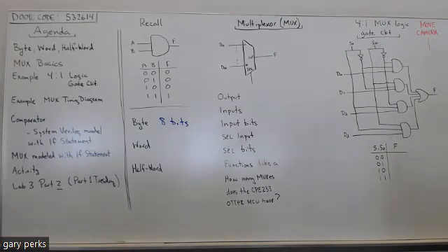So on each table, I put this diagram, and please leave the diagram on the table because I need this for my section later. But this diagram shows the structural model of the microprocessor you build in CPE 233. If you take a look at this diagram, you'll see that quite a few of the lines have a /32. What does a /32 mean on a line? 32 bits. So most of the data that's going around in this microprocessor is 32 bits. And the reason for that is most registers for that microprocessor that you build in CPE 233 hold 32 bits.